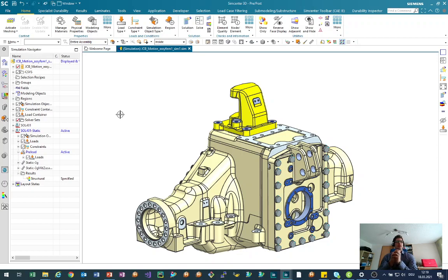We will see on the stress level of this part that we need a finer mesh representation. This is a typical example because it contains a long simulation run. This model solves about 24 hours with different load cases. Model size is about 3 million degrees of freedom, so a quite large model.